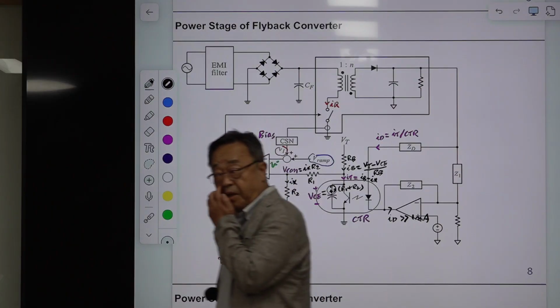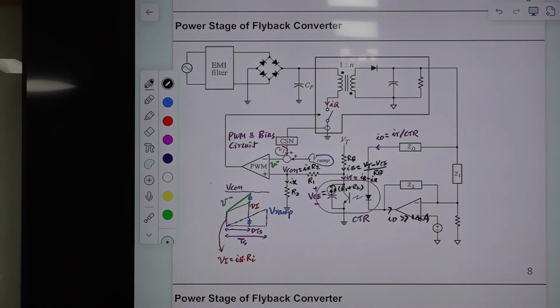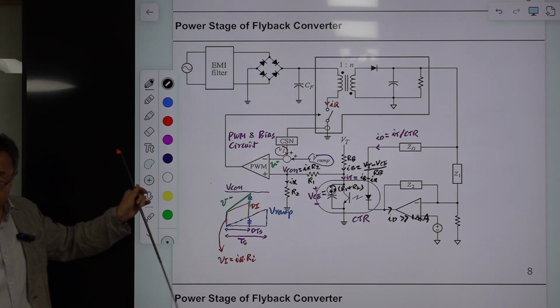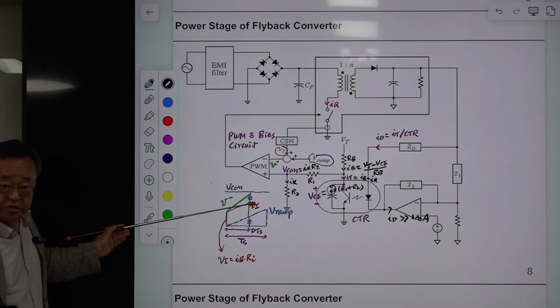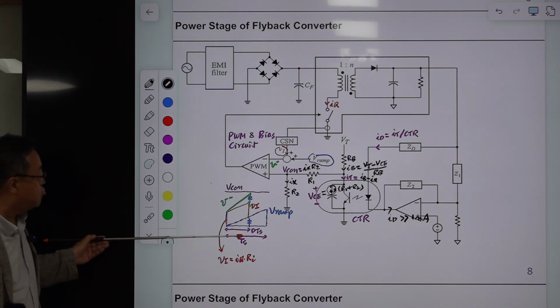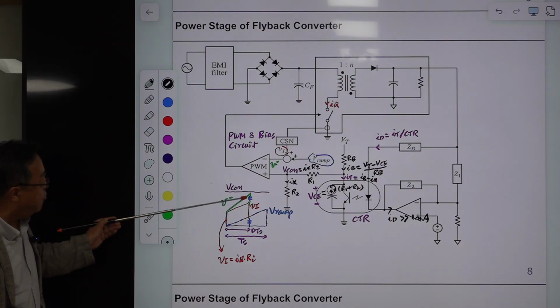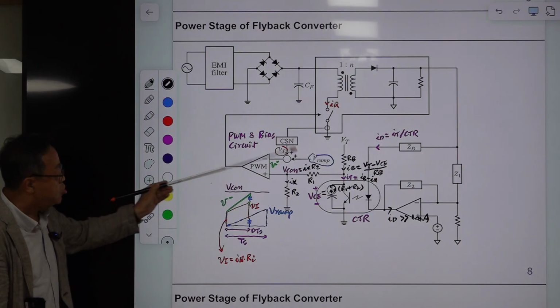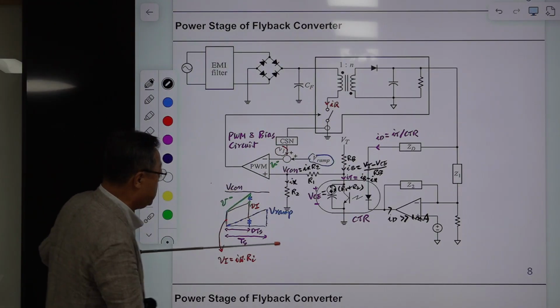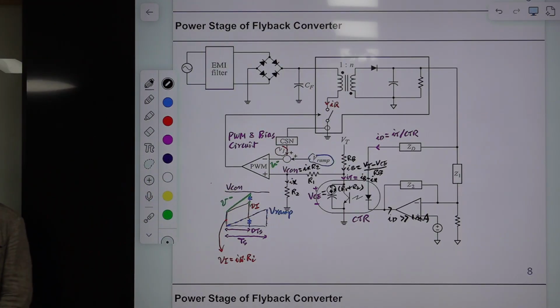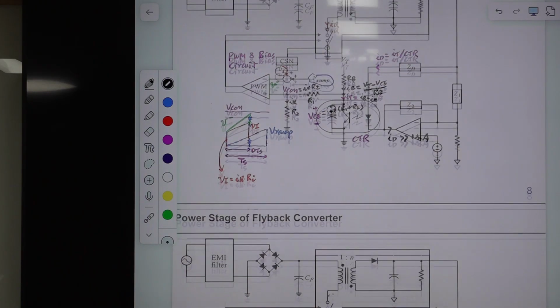This is one thing. All right. In the non-isolated converter, you don't have this. This is something extra, but not difficult. But you should understand: you determine this first, based on the required duty ratio and these waveforms, the current mode control and PWM waveforms, and the desired value of D is fixed. Then this can be easily calculated. So the first issue is resolved here, and the second issue is this one.